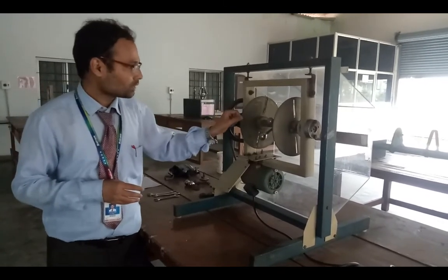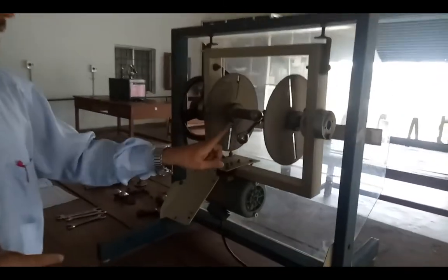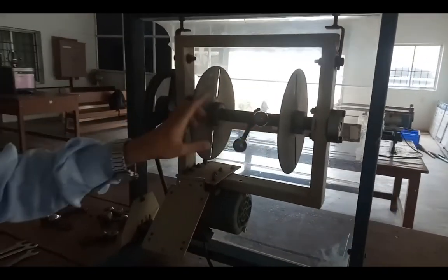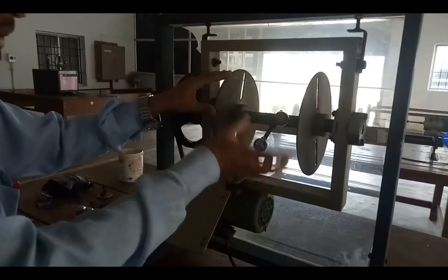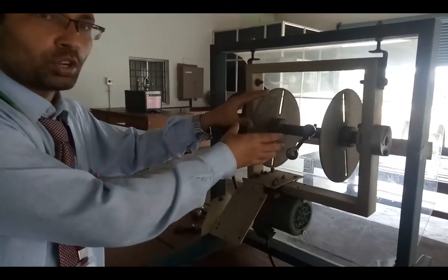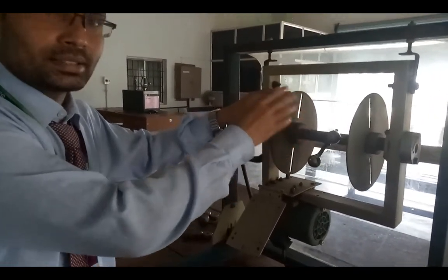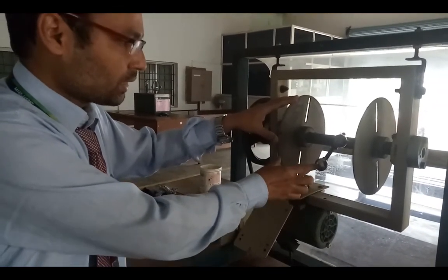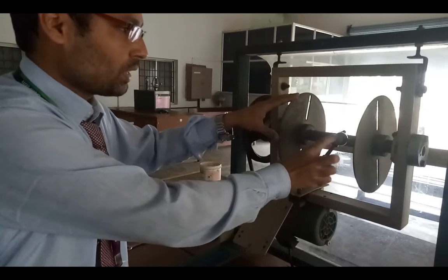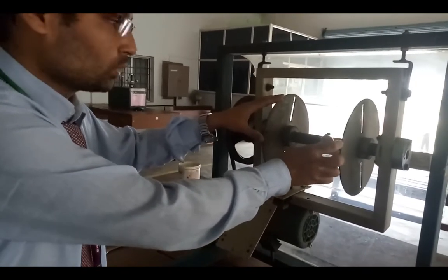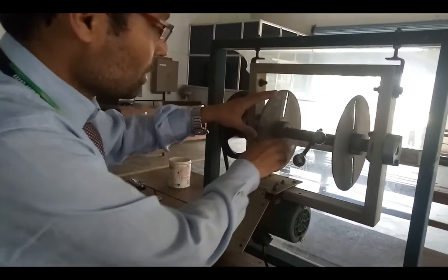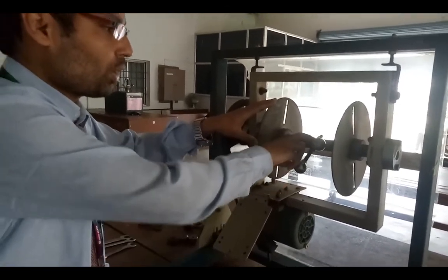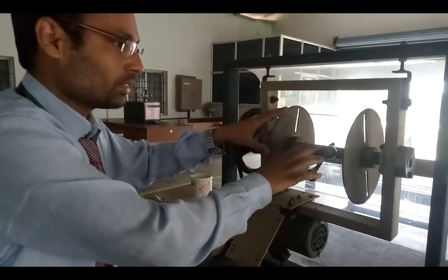These are called planes. This is plane A, this is plane B, this is plane C, and this is plane D. In the tabular column, I will explain the plane radius distance. From this point to this point, exactly the middle, you have to measure the length, and from this point to this point you measure the length. Along with that you have to measure the radius, from the shaft to this end. That is the radius of rotation. While solving the problem we are going to understand this. That is the calculation part.